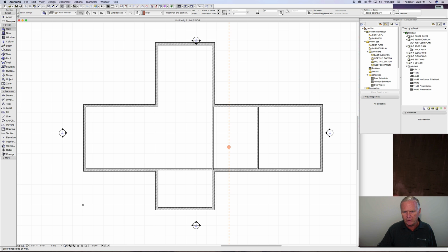Now if we go up here and pull down, we're going to be on the wrong side, because we want 6 feet in between. So we'll go down here, click on this, and we've got it on the right side. Again, you'll get used to really just whipping your mouse right up to the flip tool, and you see it's grayed out here. It can only be flipped after you've started drawing a wall. So you've got to actually click to start a wall like this, and then you have the ability to flip it to the other side.